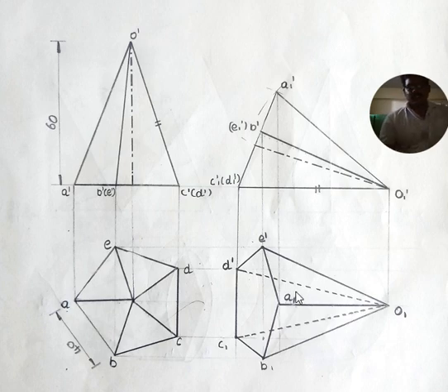In the given conditions, if we take the top view, we will get a reduced shape. At the same time, we are able to see only three slanting edges during the top view. Three slanting edges and five bottom base sides, everything is visible during the top view. But one of the triangular faces is resting, and that face containing two of the slanting edges will be invisible during the top view. So that is represented by dashed lines.